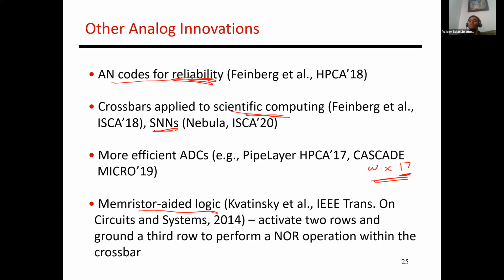All right, so if there are no more questions on in-memory computing, I'll move on to the next topic. But just as a summary to take a step back, firstly, why are we talking about in-memory computing, right? With all of these deep networks, we've already seen that the models are very large, right? And most of the energy is spent moving those large models either from DRAM into large buffers and then finally into smaller buffers and register files.